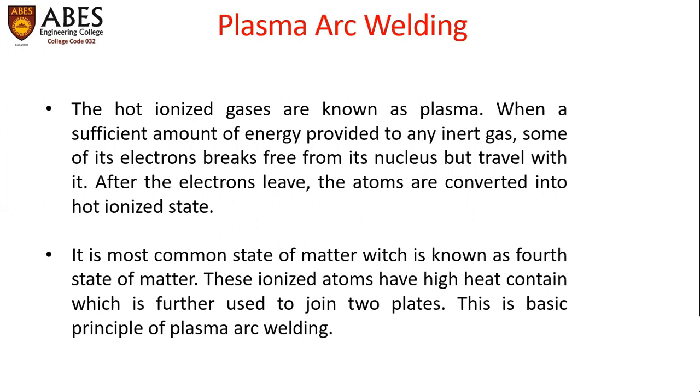Next, plasma arc weld. It is a kind of non-conventional welding process. In this process, the hot ionized gases are known as plasma. When a sufficient amount of energy is provided to any inert gas, some of its electrons break free from the nucleus but travel with it. After the electrons leave, the atoms are converted into a hot ionized state.